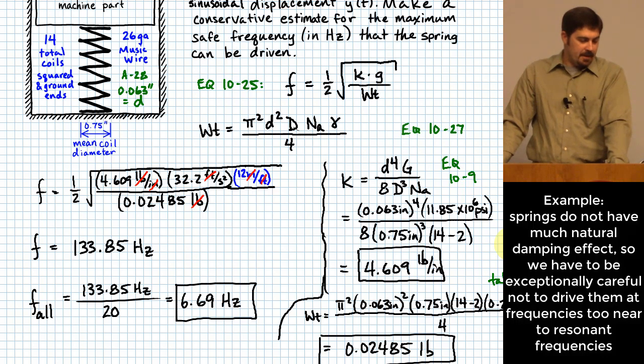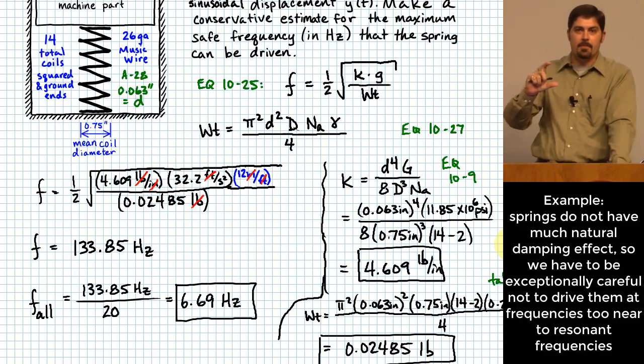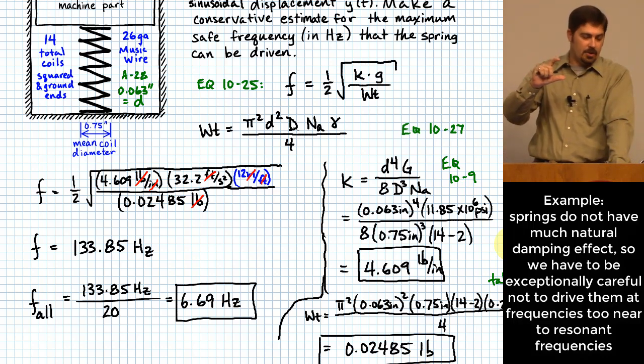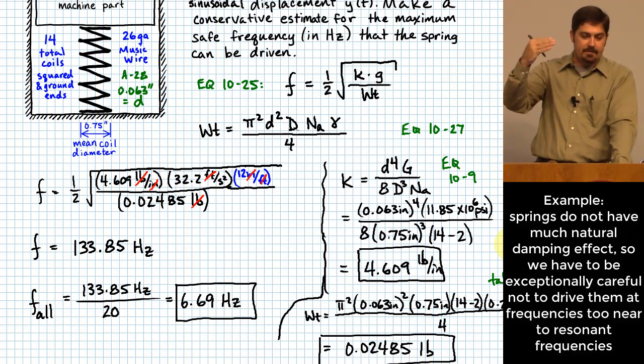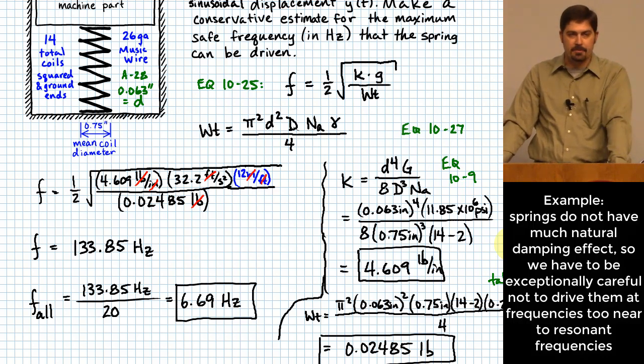Basically, the idea here, or at least this is how I take it, is that you could actually end up having standing waves in the spring that might end up having sort of a lower frequency in effect than what we just computed as the fundamental frequency here. I can't tell you more than that. I guess by testing, they've decided that this is a pretty good guideline to make sure that you're outside of that range.